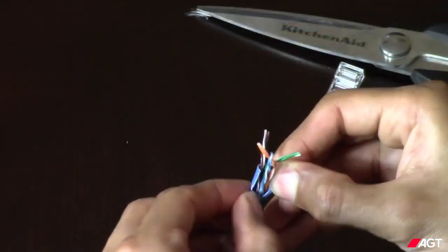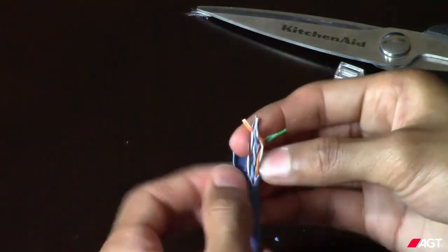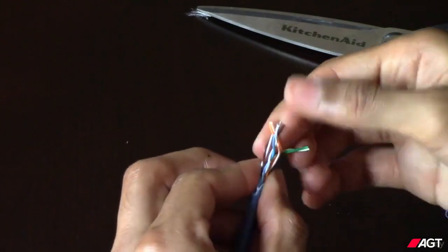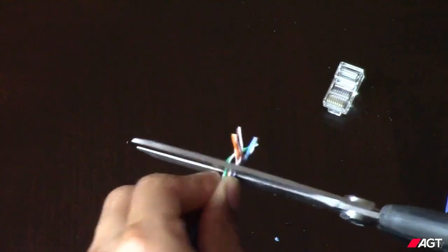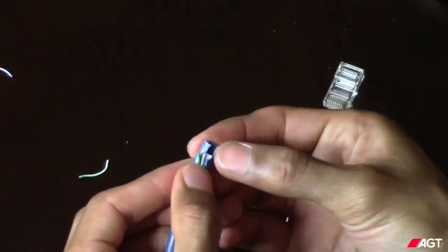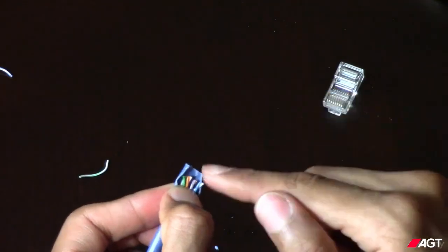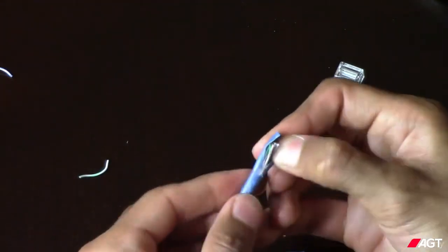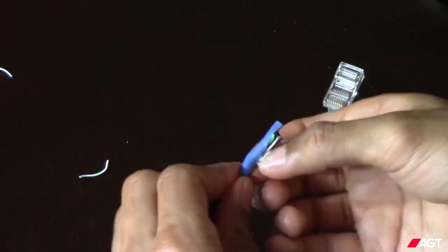After ripping off more of the sheath, you'll want to cut off the part of the wires that you spliced into with your scissors. This is what I meant earlier when I said don't initially measure with the connector. Using the part that you cut into with your scissors could save you some time, but it's ultimately going to come back to haunt you if one of your tests fail. At this point, you want to make sure that your shield is longer than your wire, just to be extra certain that there's no damaged wire left in the cable.